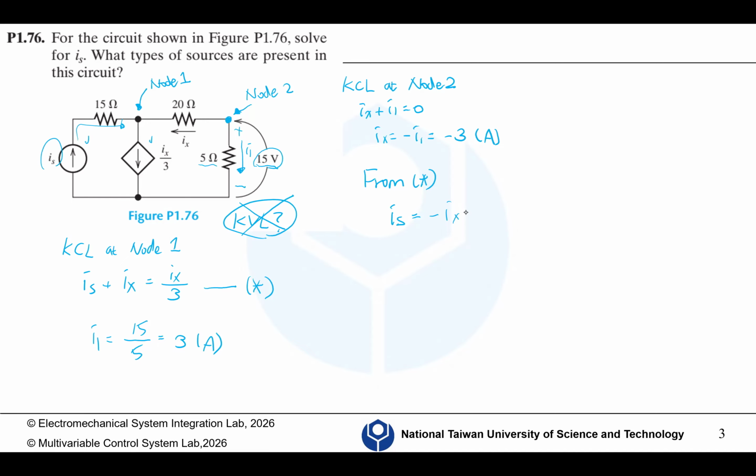I2 minus I3. And this is positive 42. So starting from the bottom left corner, we have plus 10 (I2 minus I1), plus 12 (I2 minus I3), and positive 42 equals 0. Okay, and this is how we apply KVL from the perspective of I2.